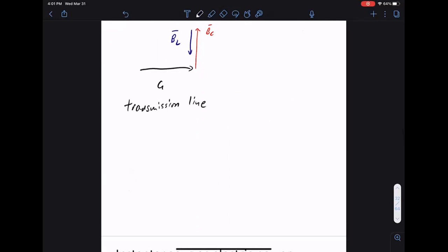Okay, so this is an actual transmission line you see, right? Let's say the overhead transmission line you look at. This is actually a transmission line from somewhere, let's say Seattle to Belleville, we build a transmission line. If we model a transmission line, what does a transmission line look like? Anybody know? The circuit model for a transmission line, there'll be some resistance for the line, of course, but then what else does the line look like? Inductive, inductance, and capacitance. It's all three.